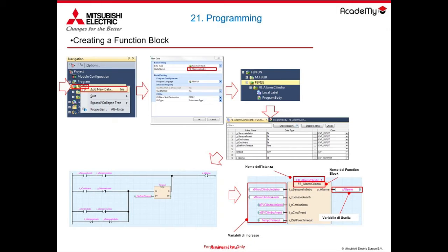This is another alarm condition, I said, so maybe here in this case I write this FB only once. Okay, I insert it into the project, and then maybe I go to recall it. I have to interface with 3 cylinders. I go to instantiate it and have 3 instances created for the 3 cylinders present in the machine.